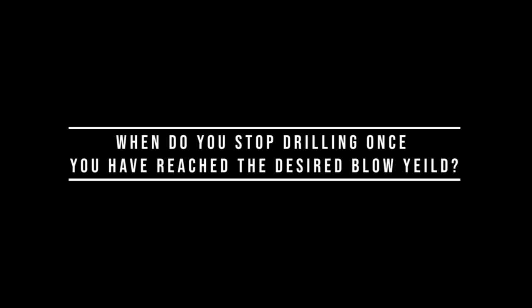And also, you've got other cases where you drill just past that fracture and you suddenly come into a rock that gives you poor quality water. Then you should even stop before drilling 10 meters past it. So the answer to that is quite dependent on the situation.